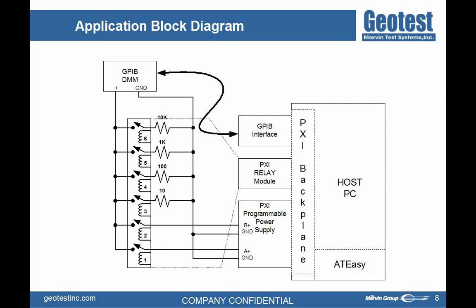Then we're going to set up channel A power supply for 3.3 volts, and take a measurement of that power supply output under various load conditions using our resistors. And then we're going to set up channel B for 5 volts and again take some measurements on that power supply output under various load conditions. So again, it's a fairly simple procedure, to try and keep it within the scope of a 1-hour presentation.